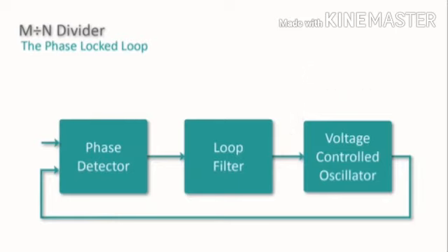Yeah, but we're not putting an FM signal into the phase-locked loop. We're putting in a pure, constant frequency. So what will we get at the VCO output? Well, we'll get a pure, constant frequency, so what's the point? Well, the point is in the feedback loop.